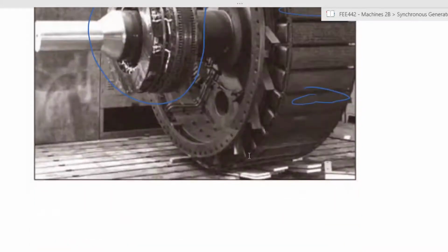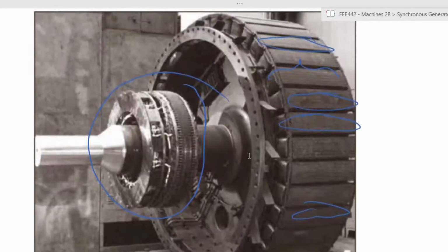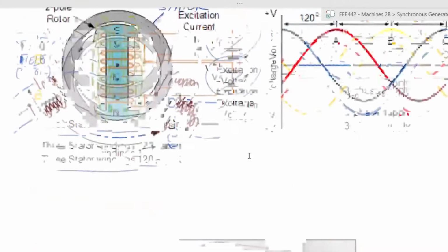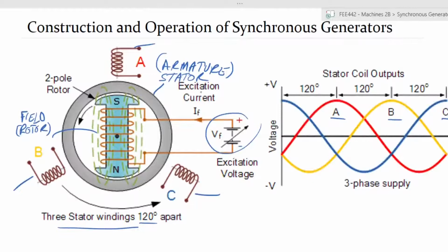In some of these cases, you will need a different kind of exciter, whereby you would want to avoid having a DC source, because generally in a power plant you would already be having the 3-phase power. If these generators or alternators are connected in parallel next to each other, you would probably have AC sources around or nearby. So we are next going to look at the exciter.